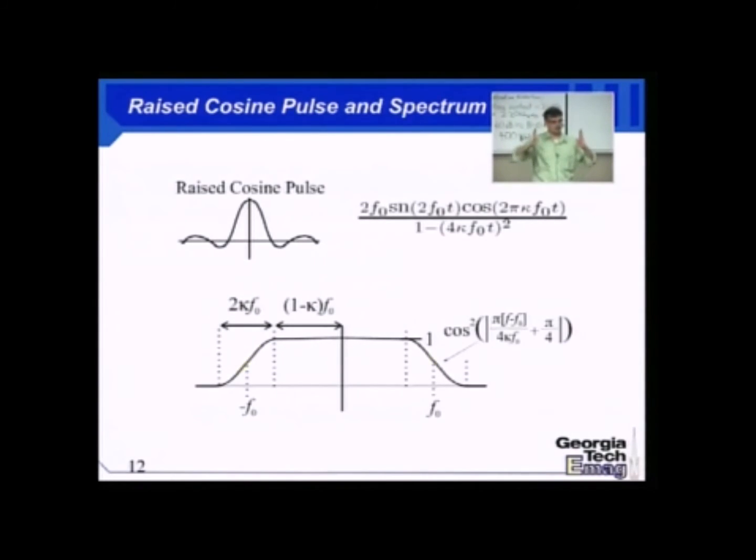Find the pulse that I can compress in the time domain the most. It has to have 4 cycles of support. But otherwise, as long as you can do that, you can compress it the most in the time domain. And what is the ultimate symbol rate and hence bit rate that will encode information and modulate information and still fit within that spectral mask of constraints? So it's a good exercise to work through.